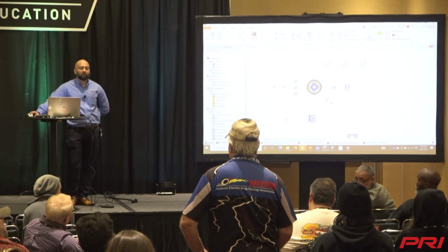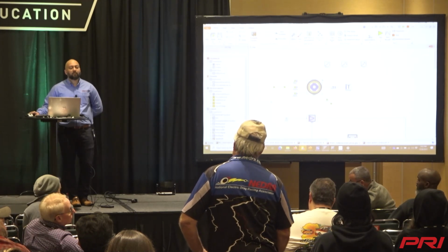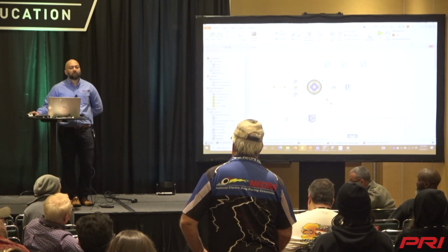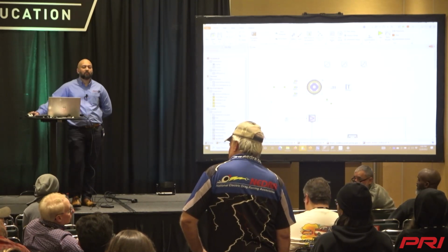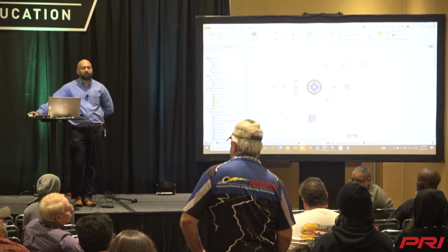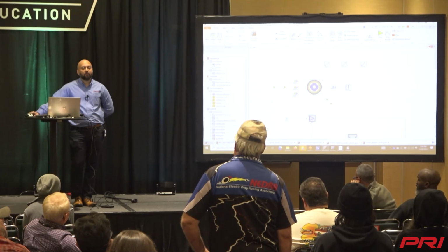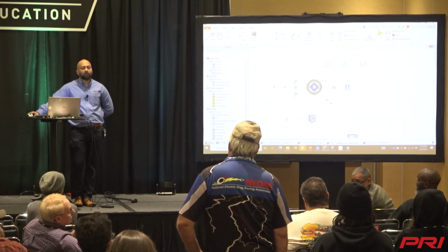I've got the specs on the tires. We've got the tires, the rear differential, and we have the motor in there. I need to get motor data because it is a one-off DC 13-inch interpole 400-volt machine. You can't do anything in your modeling unless I can give you more data, which I'll work on. Battery cells, we're working on finalizing a deal on what cells we're going to run in the car.